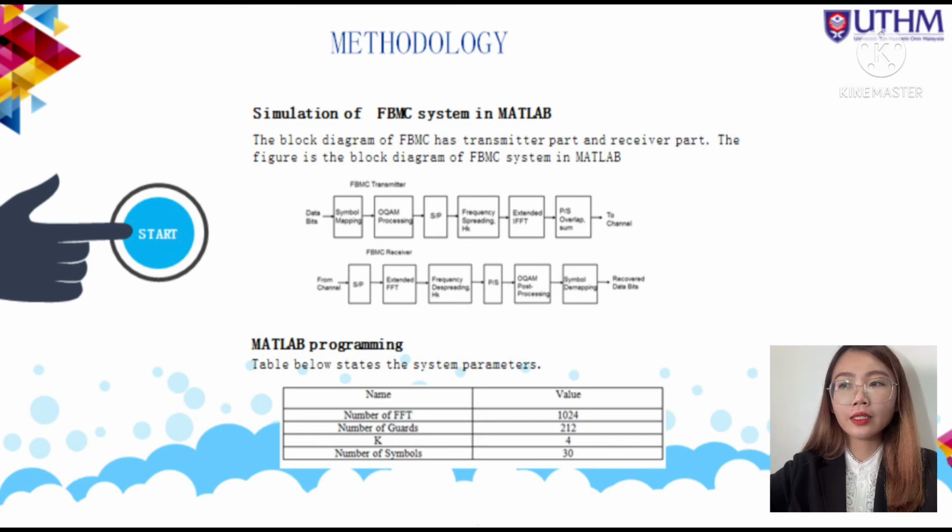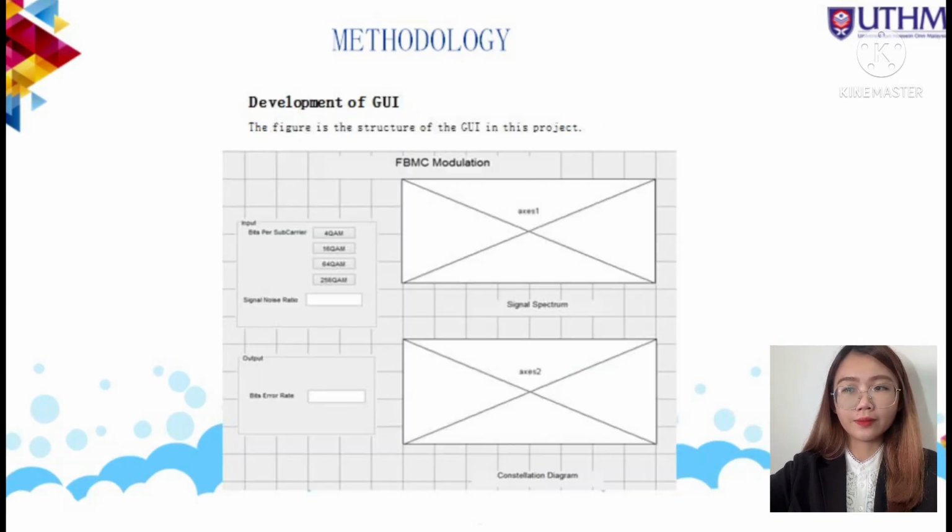After defining the system parameters, the prototype filter is applied for the zero frequency carrier and forms the basis for all subsequent subcarrier filters. The overlapping factor K is the number of multi-carrier symbols that overlap in the time domain, which is used to describe the filter.